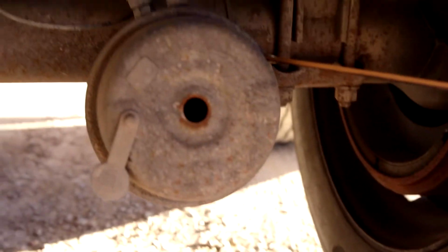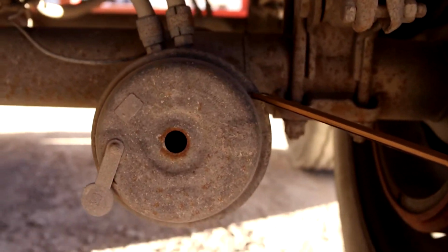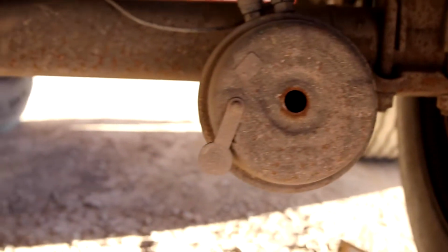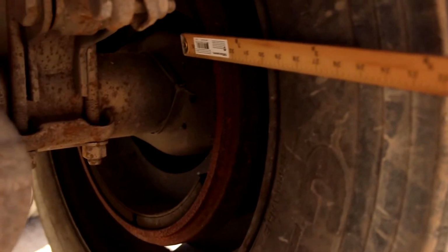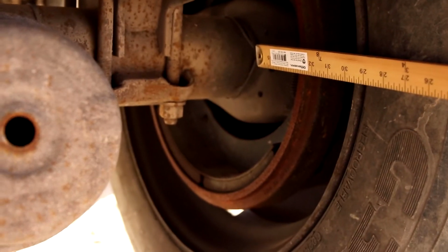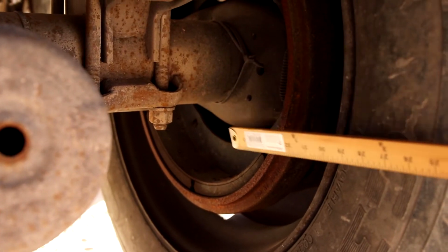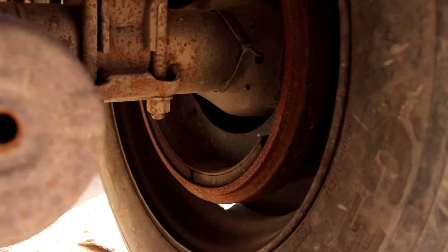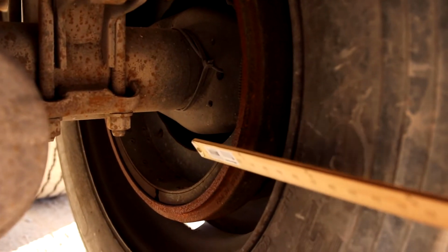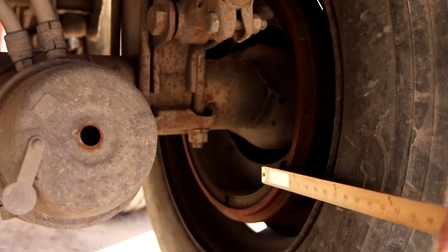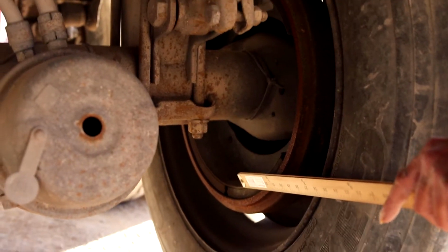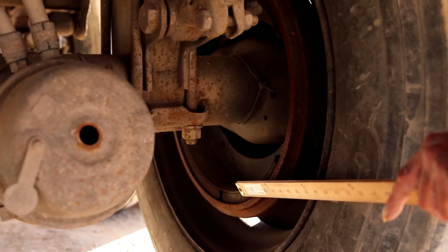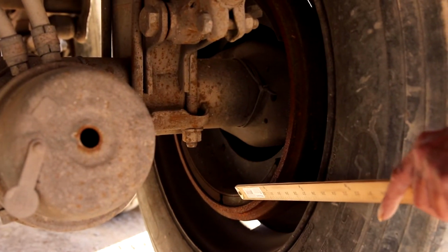This is your brake chamber, mounted securely to the vehicle, not damaged or broken, no audible leaks. Then to the inside, your brake shoes and linings, mounted securely to the vehicle, not damaged or broken, no oil, no grease, and again, at least 1/4 inch of depth on the brake shoes and linings.